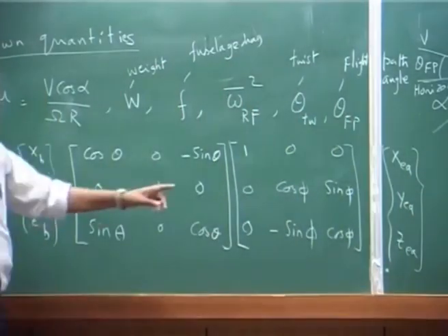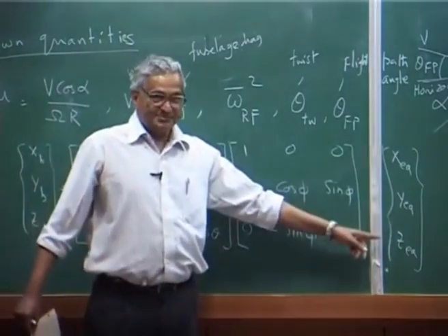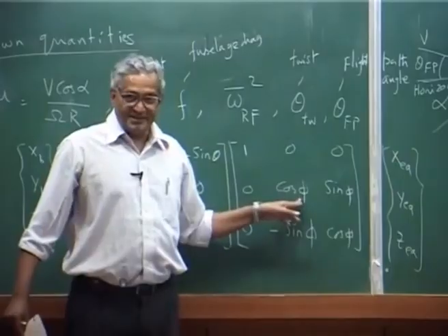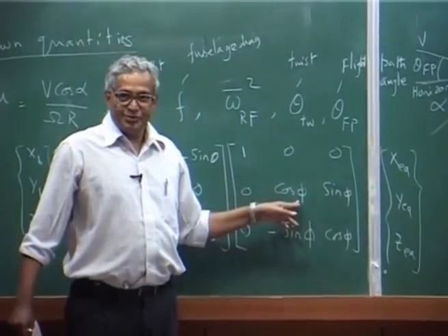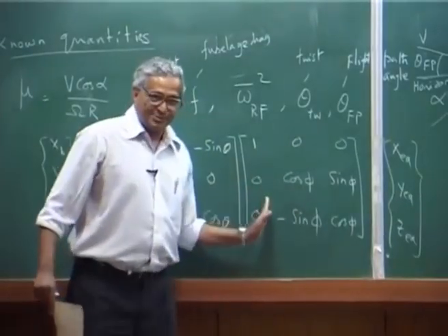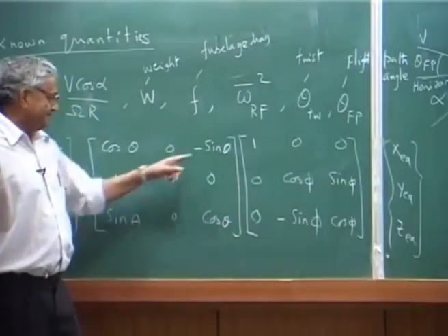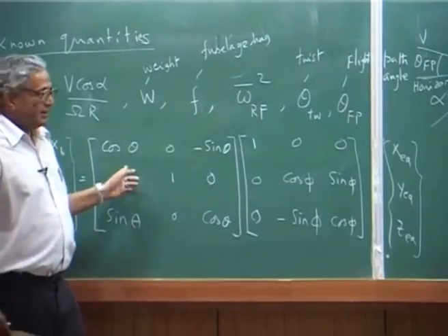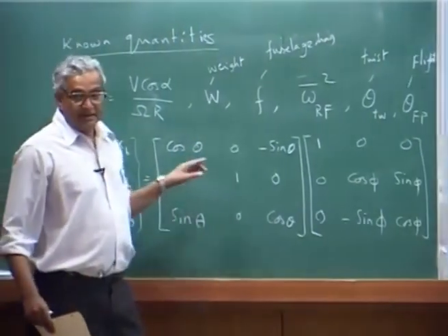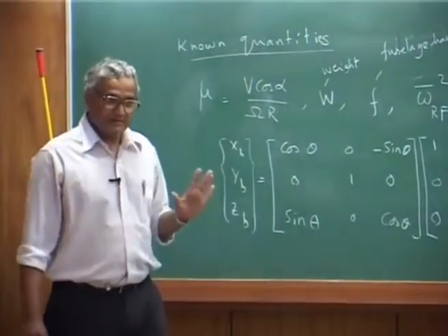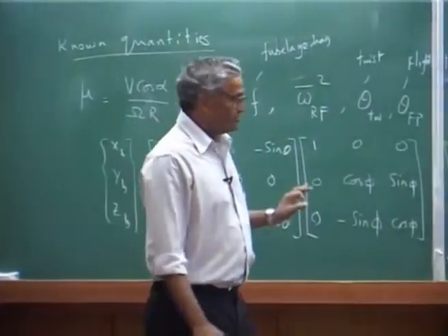This is the earth axis system, you first rotate about phi, you get the intermediate axis, then that intermediate you rotate about the pitch, but these theta are counterclockwise rotations, okay.